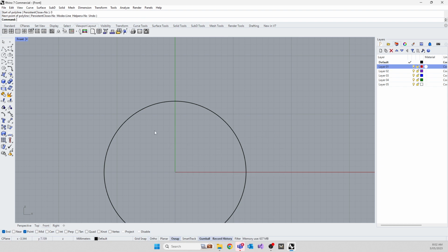So when you're going to draw two lines parallel to each other, draw here, I hold Shift, I'm going to draw it exactly parallel to the ground plane. I'm not holding Shift, now hold Shift, lock. Draw another one from there, hold Shift, lock. So those two lines are dead parallel to each other and to the ground plane, within 6 decimal places.